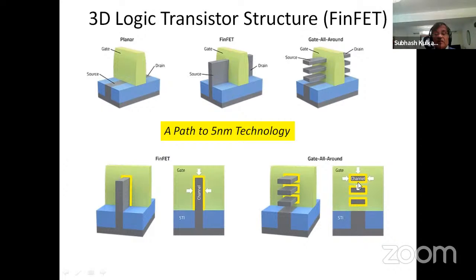So basically three terminals. You have the gate, and you have source and drain coming out of these ends of the silicon material. Schematically, this looks very easy, but process-wise it is extremely difficult, because these channels are about 5 to 10 nanometers thin. And the question is, how do you make that with the uniformities that we need?